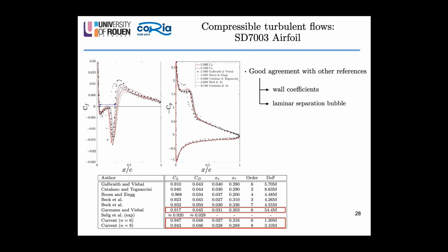What is actually interesting is that we also considered implicit LES of this configuration, and since we used a 6th order and 8th order simulation, both simulations were unstable. And once again, this reflects what I said before, that implicit LES, sometimes for relatively high order of approximation, are not really reliable, and they can be unstable since you have a very small amount of numerical dissipation.